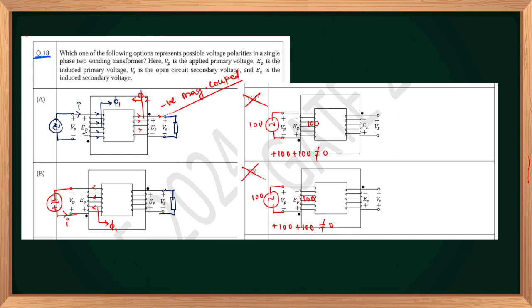He mentioned that the polarity of the voltage at the load is positive here. That means the current is leaving here now. The secondary is acting like a source now because it is going to deliver current to the load. So if the current in the winding is in this direction, then the flux produced by the secondary winding is going to be in this direction.